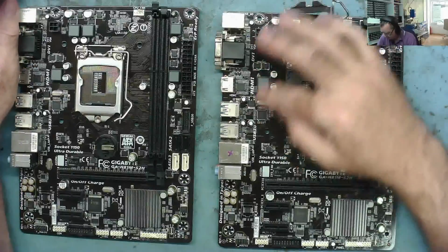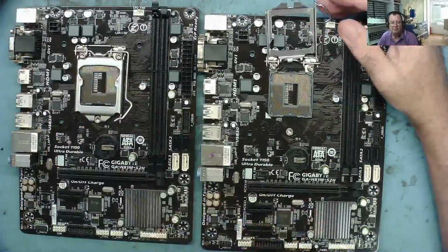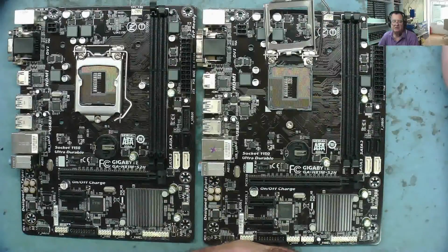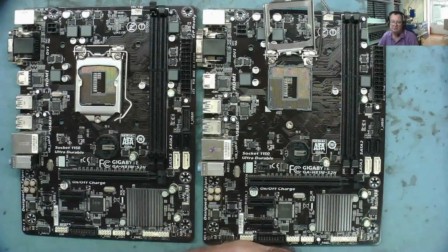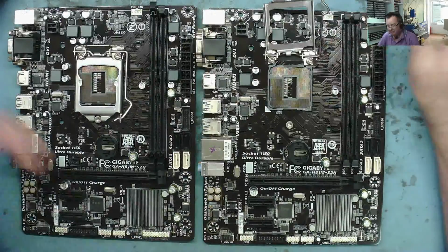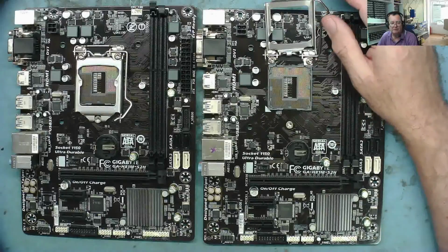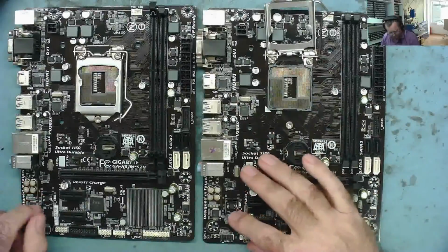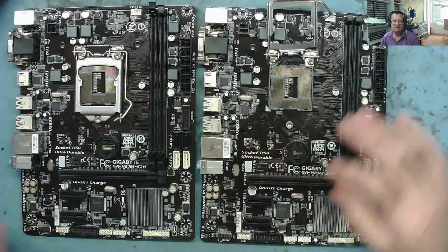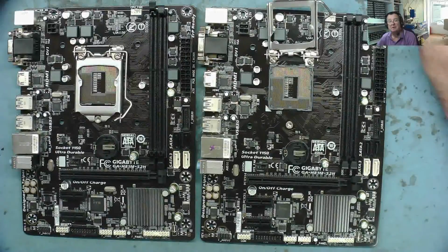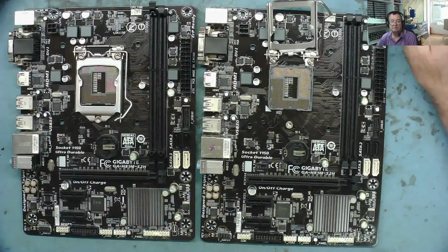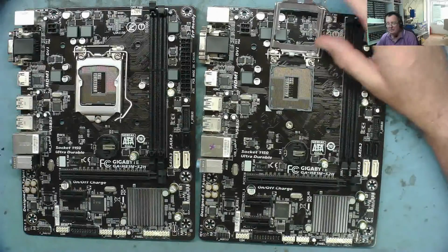The other one is stuck in some sort of boot loop, so the fan comes on, spins for some seconds, goes off, powers on, some seconds, powers off, continually in a loop. And one cause I've seen for this recently has been corrupted BIOSes on Gigabyte motherboards. Normally they have a main BIOS and a backup, but these only seem to have a main BIOS. I'm not sure these even have the two BIOS, but even the ones with the main and the backup, I've seen them, they don't seem to be that reliable. They get corrupted and you have to take off the BIOS chips and reprogram them with an EEPROM programmer basically, and then they work. So I've done that quite a few times and it's worked.